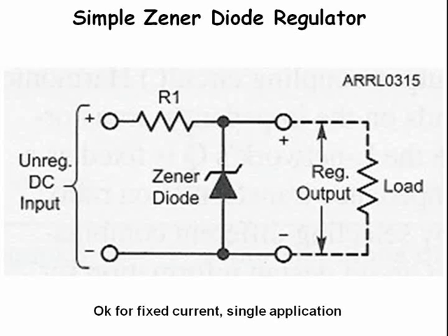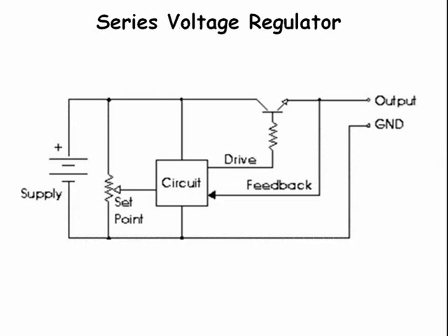A Zener diode's reverse breakdown voltage is fairly constant. Zener diode regulators work best with a constant load. Pass transistors can often be used as the voltage dropping element rather than a resistor. The DC current in the base of a transistor is used to throttle the collector emitter current. This is an example of a series regulator because the pass transistor is in series with the load.